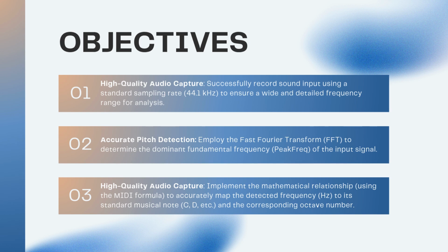Objective 2: accurate pitch detection. This is the core engine. We utilize the power of the Fast Fourier Transform, which is the foundational algorithm in digital signal processing, to mathematically determine the signal's dominant fundamental frequency, which we call peak frequency.